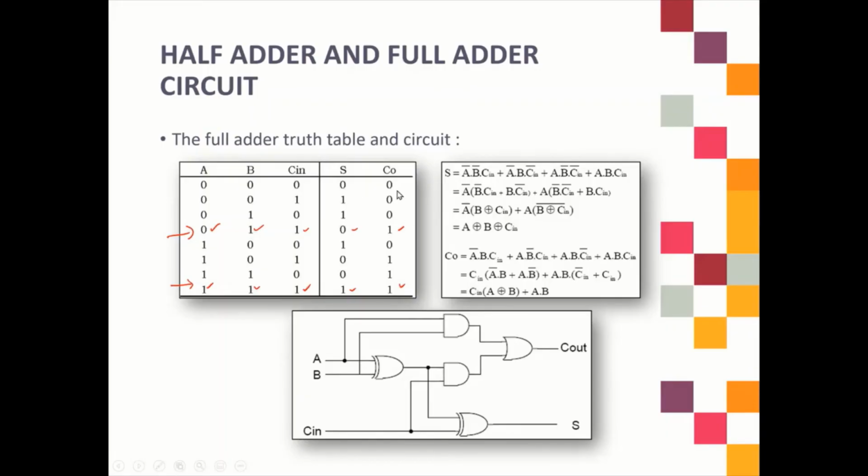So the next step is simplification of your expression. This one is actually using Boolean algebra. You write the SOP and then you simplify. The first step here is factorizing between these two product terms, and then between these two also use factorizing. So here you factorize A bar, and then here you have A, and then this is the value in the bracket after you factorize. Right, so next step,